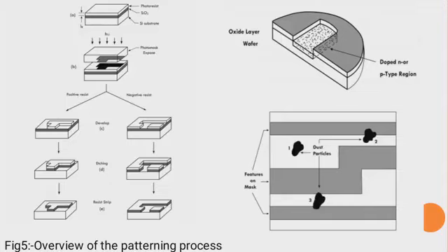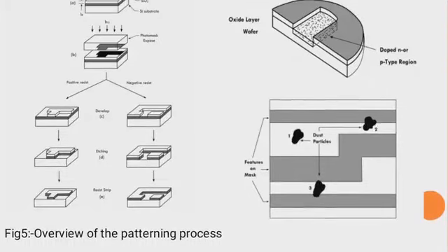Patterning, which is one kind of lithography, is one of the most important steps in IC fabrication or wafer fabrication. By this kind of step, we can selectively collect, mask and expose portions of the surface for deposition, doping or etching. It sets the critical dimensions of the device.